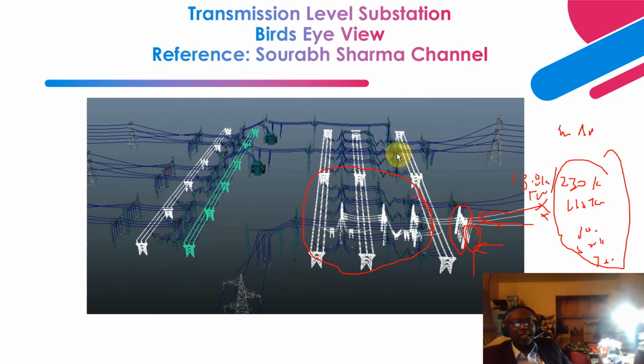As soon as it senses an overvoltage condition based on its rating, right, it clips the voltage. Once it clips the voltage to the required clip voltage, it changes from a high impedance operating characteristic to a low impedance characteristic so that it can conduct the discharge current from the short circuit to ground.